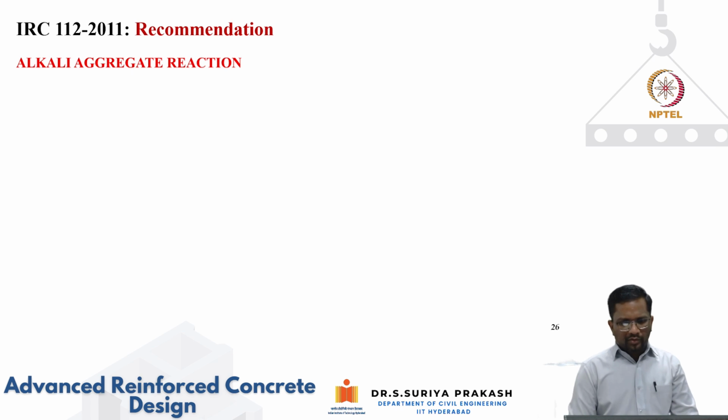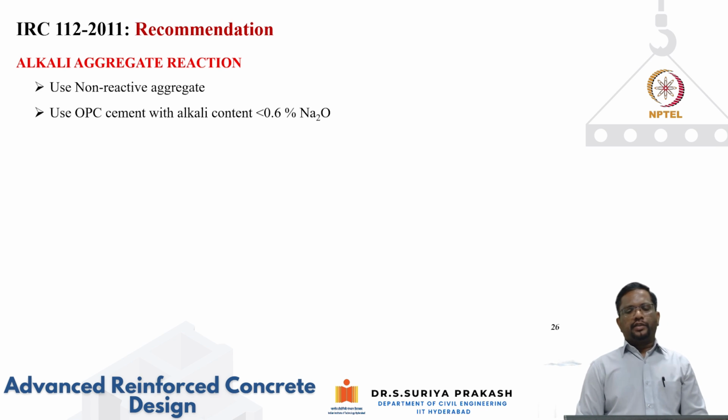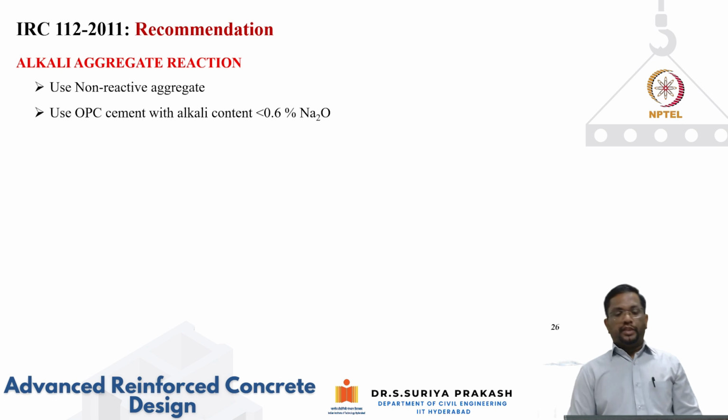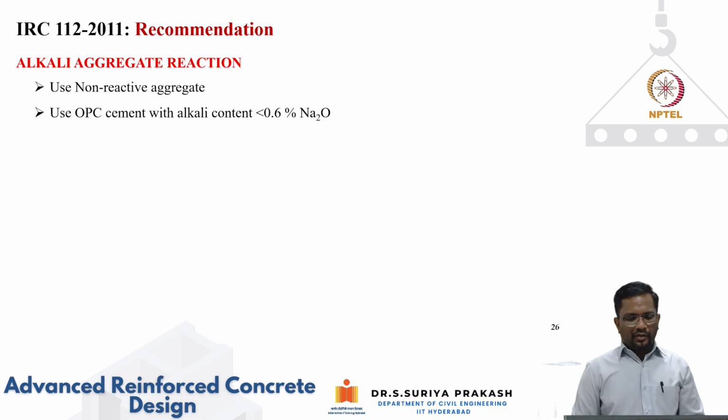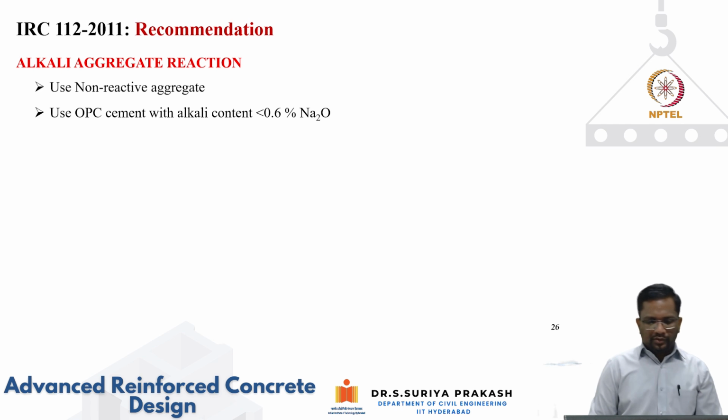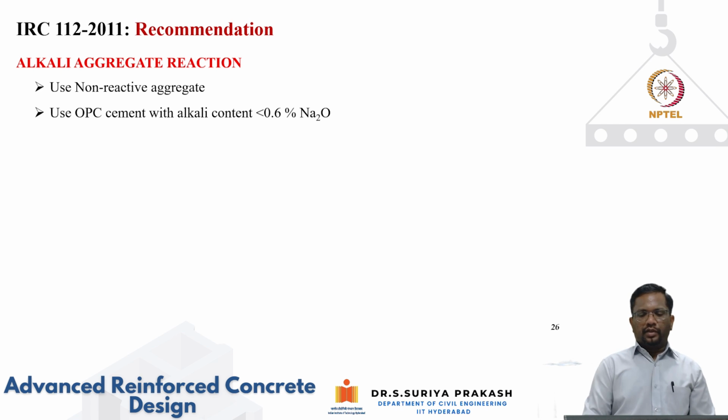Now, let's look at IRC 112 recommendations for alkali aggregate reaction. It says that we need to use non-reactive aggregate. We also looked at it: we can do petrographic or microscopic examinations to find whether any reactive silica is there in the aggregate or not. They are recommending using non-reactive aggregates, and also using OPC cement with alkali content less than 0.6% of sodium oxide.